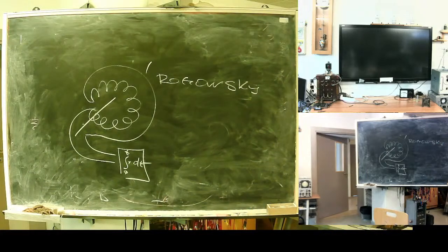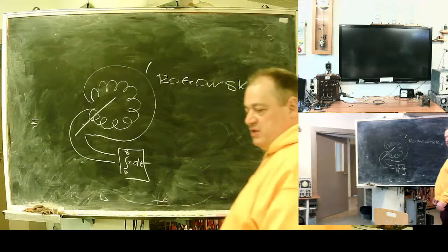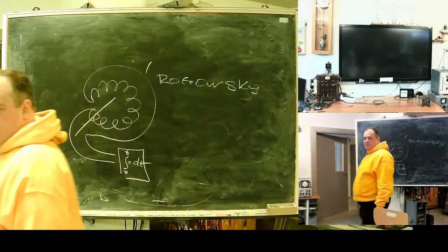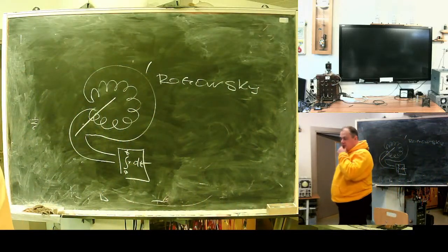The good thing about Rogowski coils is that they are very linear. The bad thing is absolutely zero load capability. So without its protective device, a Rogowski coil is useless. It cannot be used as a current transformer where you can plug in, I don't know, an ampere meter or multimeter.